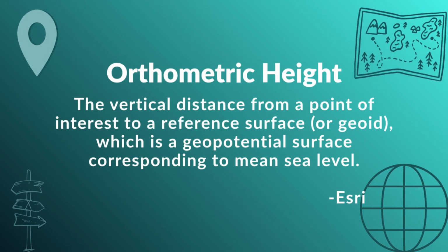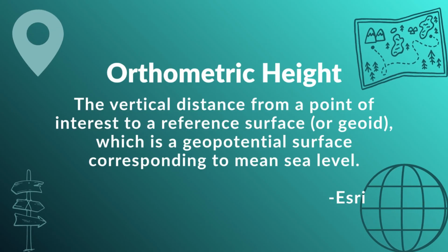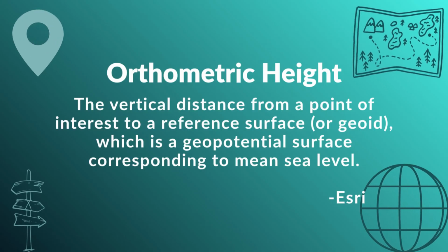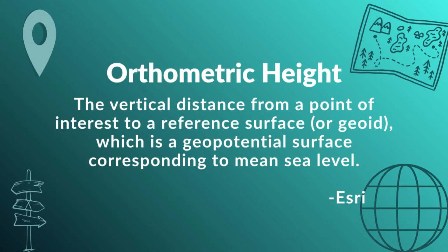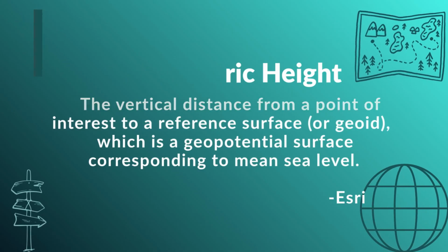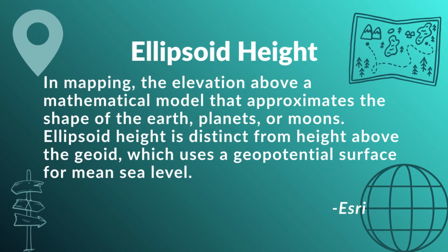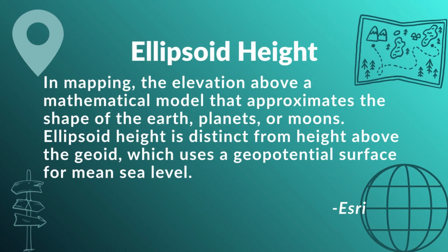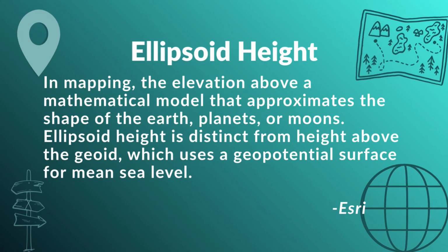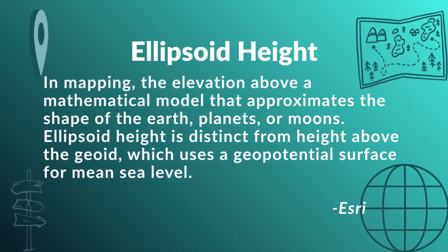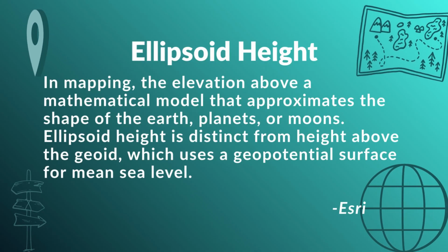When a topographical map lists a mountain peak at, say, 10,000 feet, it is referencing orthometric height based on mean sea level. But if you walk up that same mountain with a raw GPS receiver, it will not give you the orthometric height, because a raw GNSS reading gives you the second type of height, which is ellipsoidal height. Exactly. As the name implies, this is strictly the height above the mathematical idealized reference ellipsoid. It completely ignores the localized gravity field or sea level.